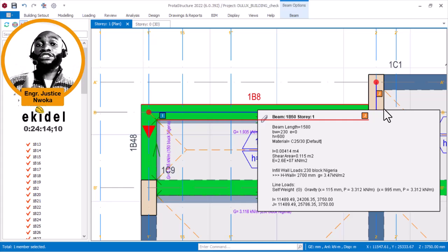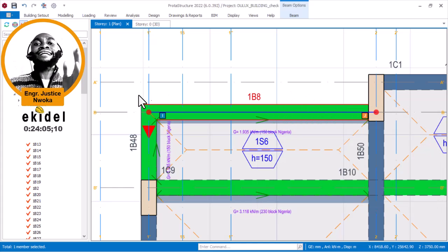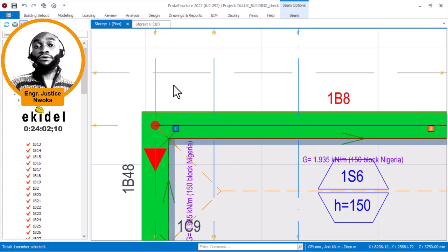If you're a student watching this right now, let me recall your memory back to when you were taught structural analysis and end conditions: the moment at every end of a beam tends towards 0. The moment at every end is equal to 0. So knowing that the moment at every end of a beam is 0, that means every end of a beam is meant to have 0 moment, and the only thing that gives you 0 moment is a pin end or a hinge end. Pin and hinge still mean the same thing.